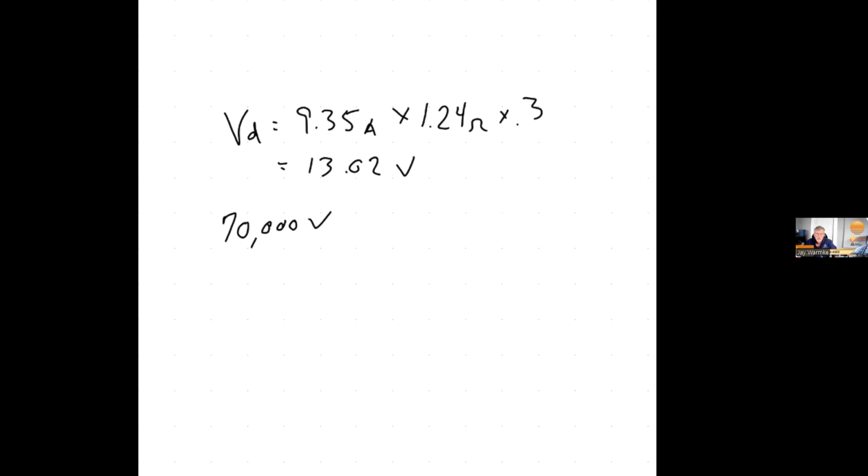So the higher the voltage of the system, the less impact voltage drop has on your system. Which is one of the arguments in favor of going to 1,000 volts or 2,000 volts or 1,500 volts or whatever in these systems, because voltage drop becomes less and less of an issue. But here in the US, we've decided 600 volts is what we want at the residential level. And I keep thinking that's going to change, but so far it hasn't. I think there's an embedded manufacturing base that would just as soon not have that change. So that's why we're dealing with some of that.